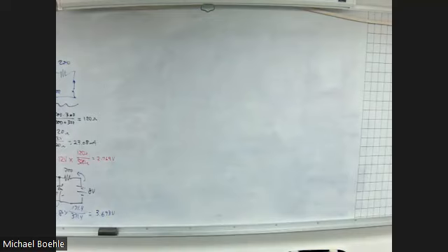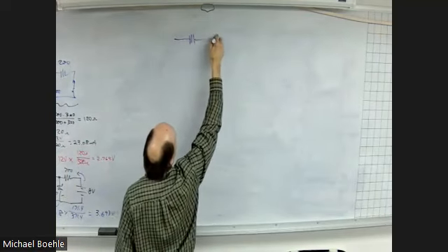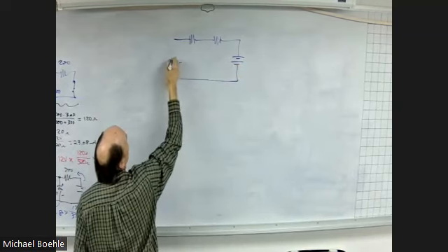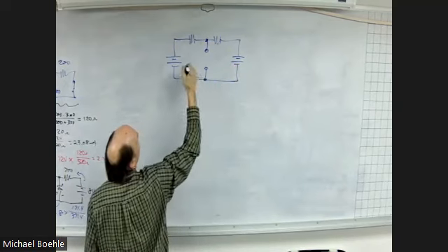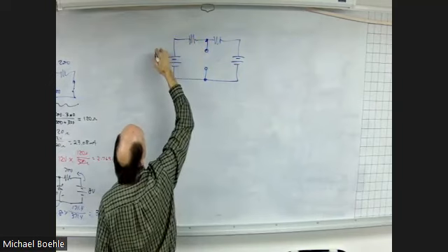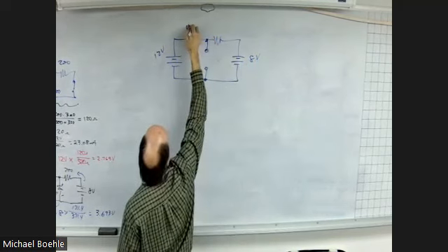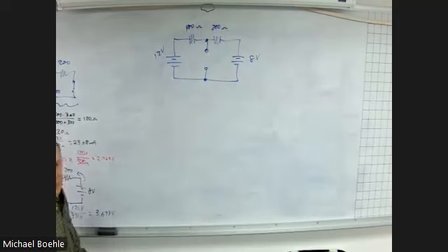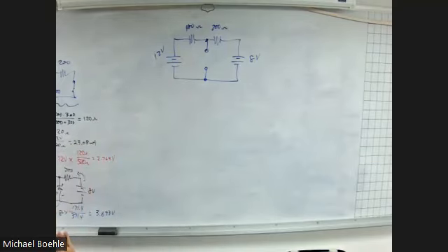All right. So we're going to Thevenize around our 300 ohm resistor. What that means is I remove it. Take it out. So I'm looking for 12 volts, 8, 400, 200. What am I doing? Well, if I'm Thevenizing, I'm looking for what the voltage would be between those two points with nothing there.